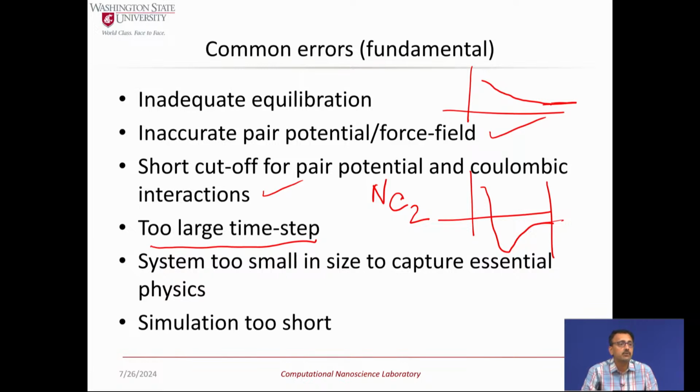One is obviously the compute efficiency. If you use a time step that's needlessly small, then your simulation will run longer, obviously. On the other hand, if you're using a time step that is too large, the system might not be able to converge. So a lot of times you have to run a sensitivity analysis to make sure you're using the right time step. It can also be related to the physical or chemical process you're investigating. A chemical reaction, for example, you might need to look at resolution at much smaller time steps, typically 0.1 femtoseconds, to capture a certain chemical reaction you're interested in.